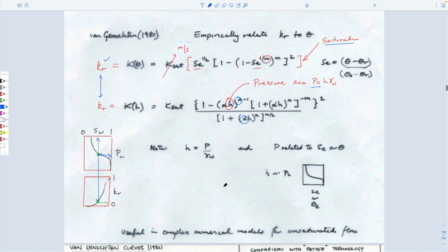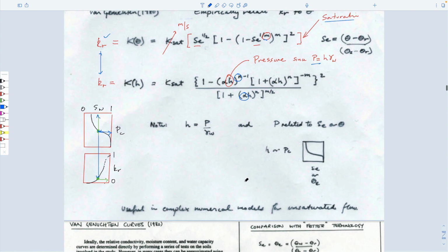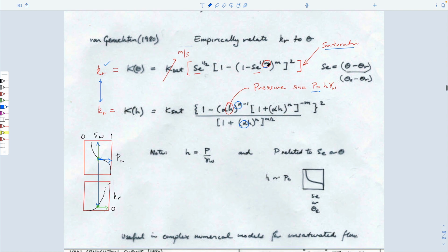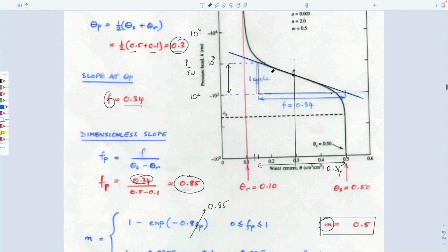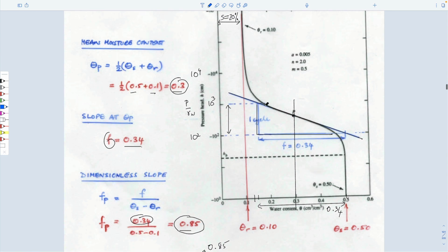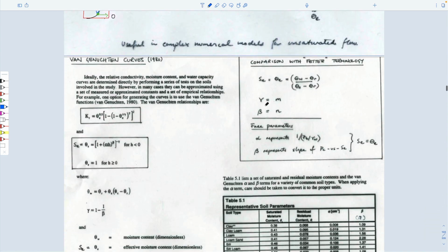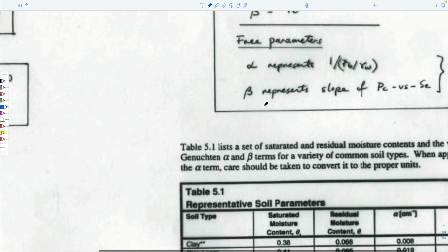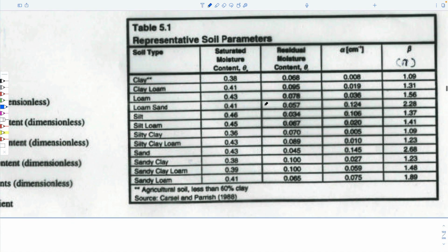Okay? So that's it. And so I guess the final word on this is that if we knew these values of these empirical coefficients, not from having a capillary pressure versus saturation curve, but from someone else before us having done that and relating it to something else like the gradation, then we could use that data, those data, plural, to say something about what those empirical coefficients are.